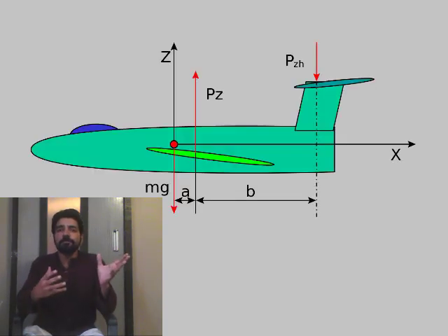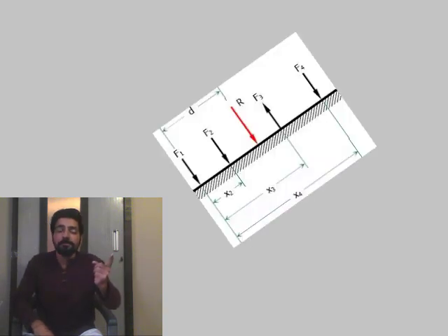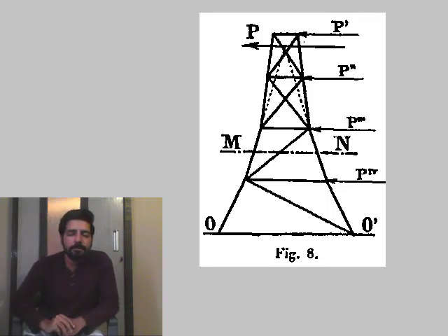It is very easy to identify. As you can see, it does not matter what the shape of the body is. If all the forces have same direction, as you can see here, all the forces are vertical, then it's a parallel system. Now you can see all the forces are inclined at the same angle, hence they are parallel. And now you can see all forces are horizontal and hence again parallel. So that's all about how to identify a parallel system.